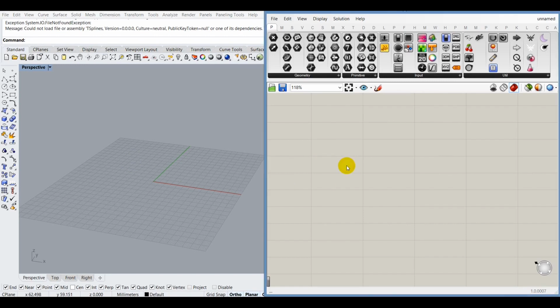So let's see, how do you create a small component or a small script in Grasshopper? What's the logic? Let's take a look at that right now. You can actually select any of these tabs on the top, select any of these components and just bring it in on your canvas and start working. But there are two ways of bringing in a component inside your Grasshopper canvas. The first way is I can easily go to any of these tabs.